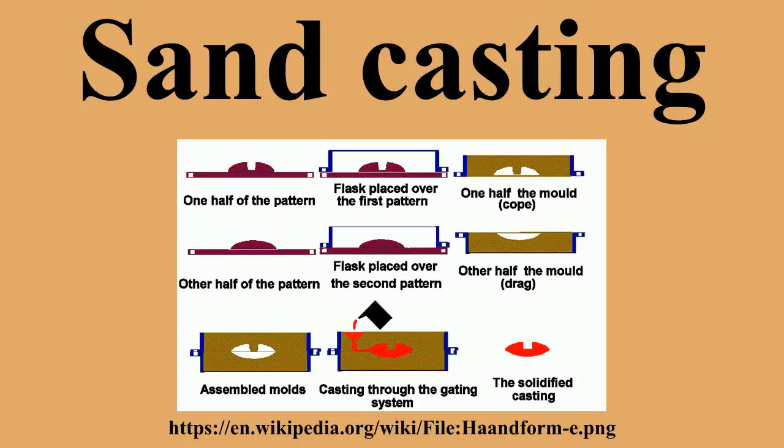No-bake molds. No-bake molds are expendable sand molds, similar to typical sand molds, except they also contain a quick-setting liquid resin and catalyst. Rather than being rammed, the molding sand is poured into the flask and held until the resin solidifies, which occurs at room temperature. This type of molding also produces a better surface finish than other types of sand molds.